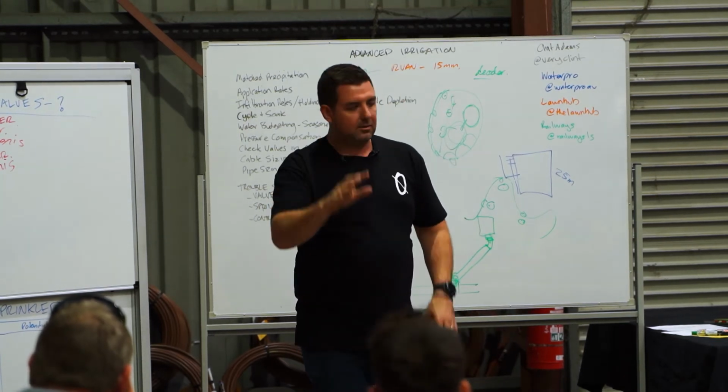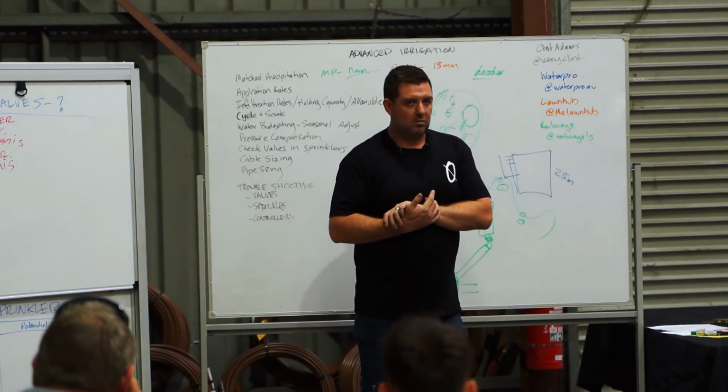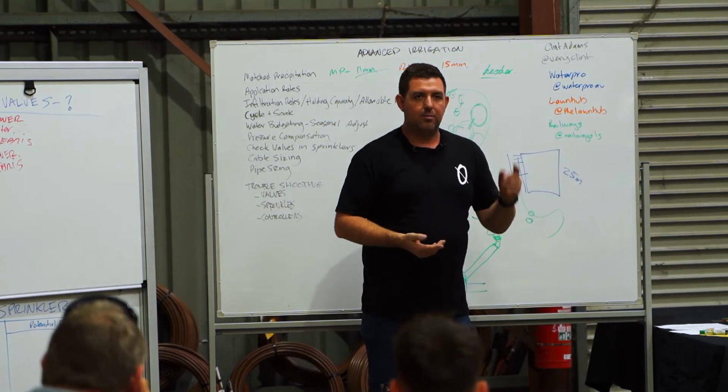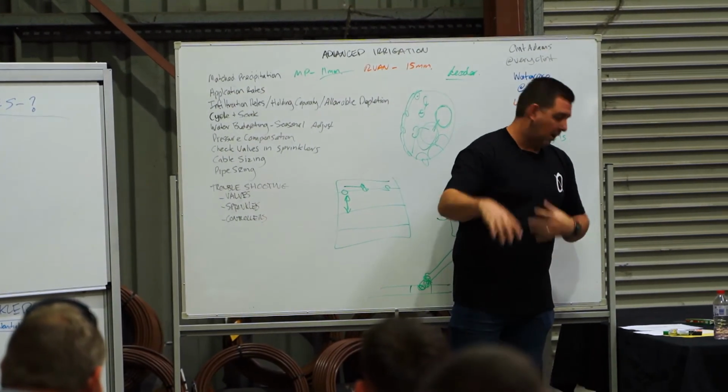Anti-clockwise brings it all the way up and stops it pushing on the diaphragm. You can do that without having to get any tools out, you're not cutting anything open. So that would be the first thing I'd look at if you're not getting enough flow, before you start opening the valve.